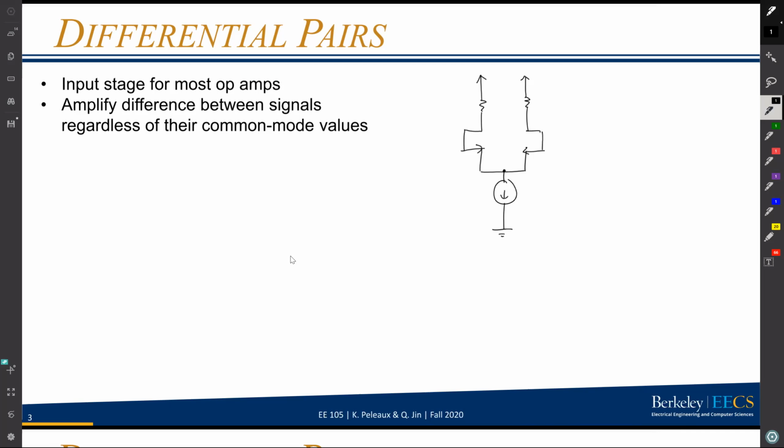What you will see if you continue to study analog circuits is that oftentimes that bias configuration isn't used. Instead, we'll use a current source to establish the bias current. That current source then sets the operating point, and we can determine VGS and VDS from that. You'll still need some sort of load. I say load because we know in small signal, these RD resistors are going to go to ground if this is VDD up here, right? But that load, as I'll talk about in a little bit, doesn't actually have to be a resistor. It could be another transistor.